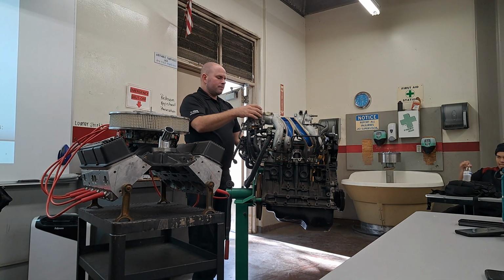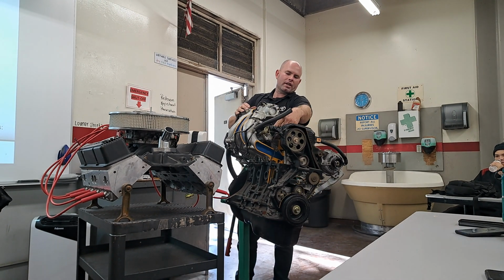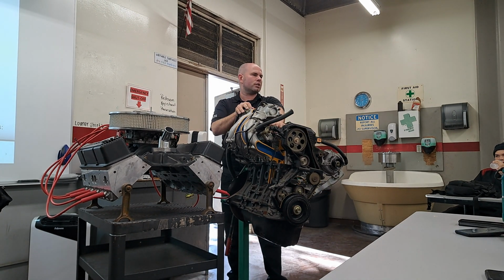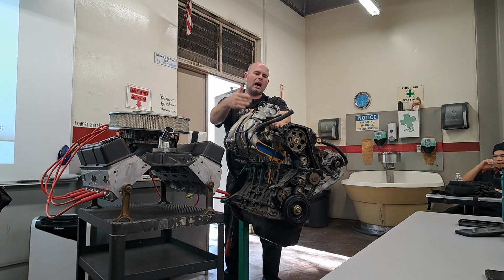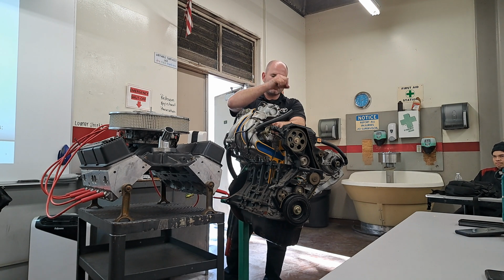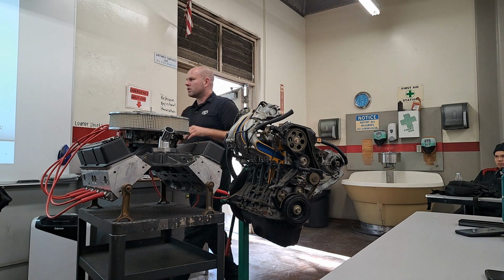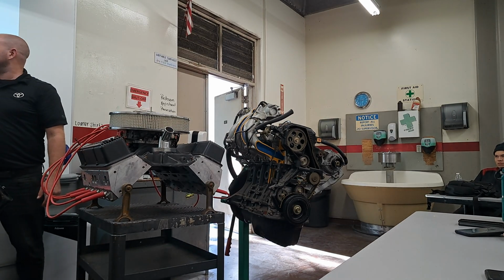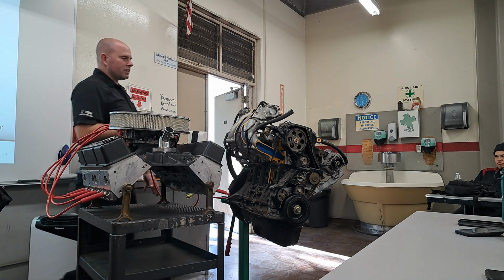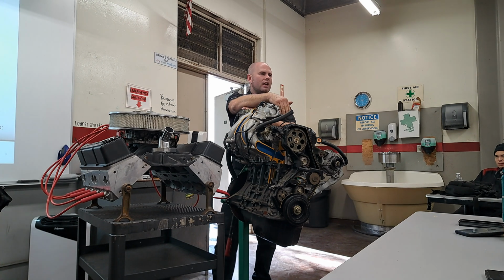Now on this one, it's a little tough to see, but it's got a fuel rail right in here. So this is port fuel injection. All this stuff here is dry. There's no fuel until the fuel injector sprays, and it sprays right at the intake port. What's the intake port? Well, you can kind of see it right here. This is a passage that's built into the head. The intake port is where we ultimately flow into the intake valve, and that goes into the head, which is the top of the combustion chamber.